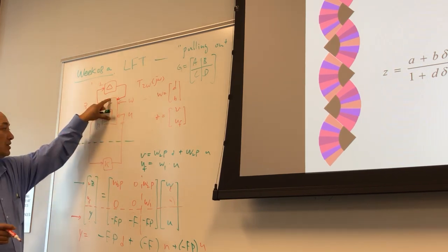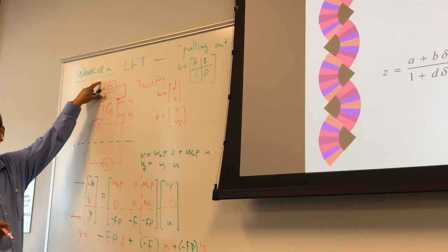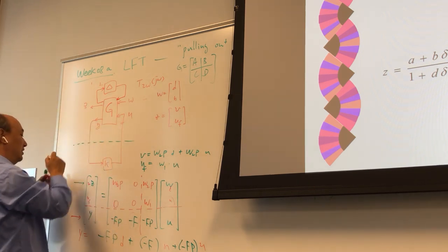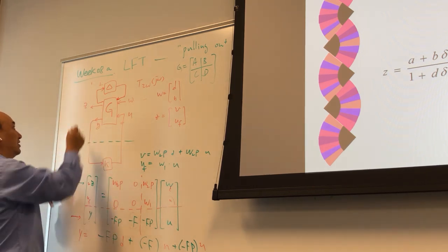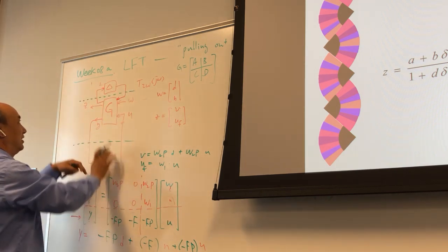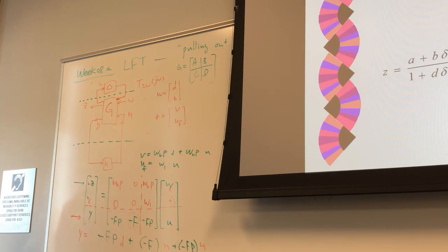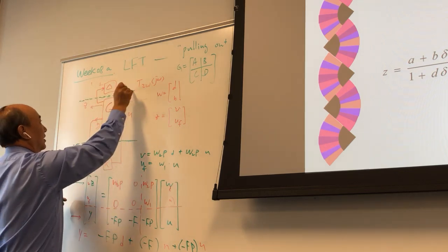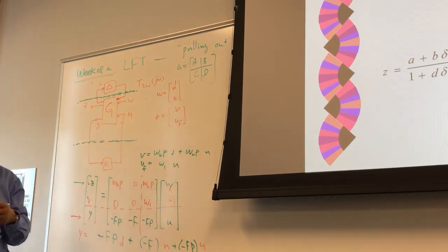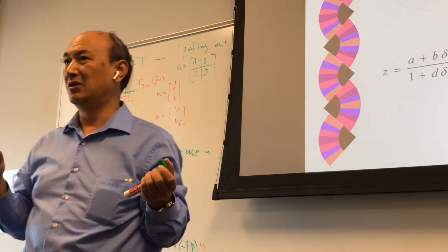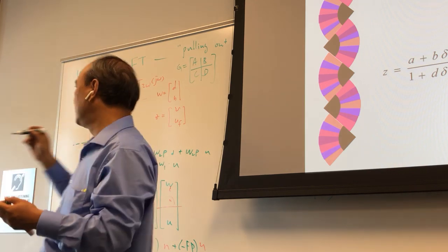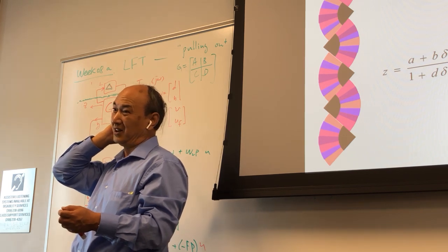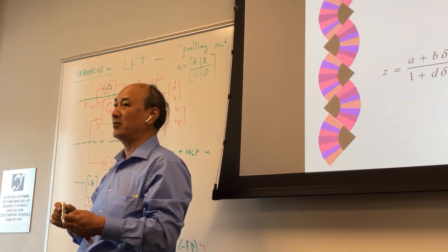So you have a nominal system, controller, uncertainty. I hope at this point this picture makes very good sense. And again, you feel there is a systematic way to pull out K and pull out delta at this point. Just follow this principle, and you can make these two separations without getting very confused. Because we're talking about MIMO, and we also want to leverage the structures inside here, this LFT framework is absolutely useful.